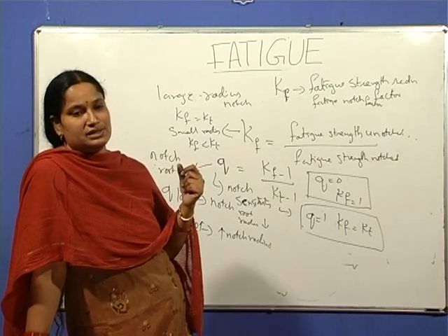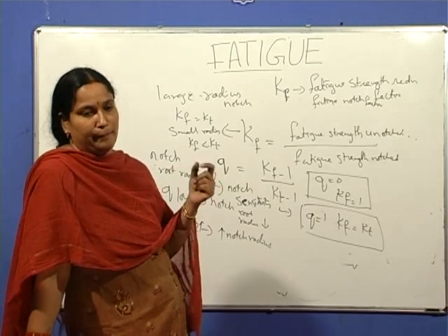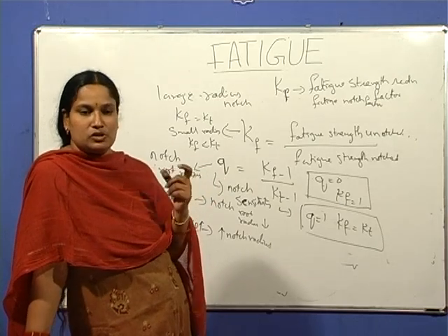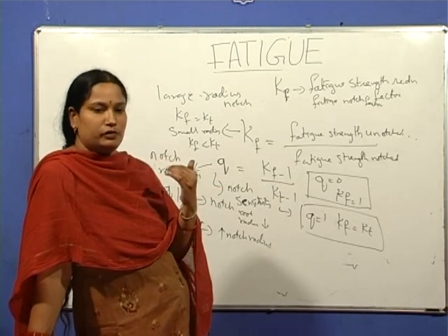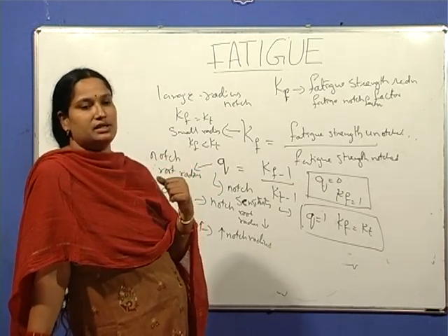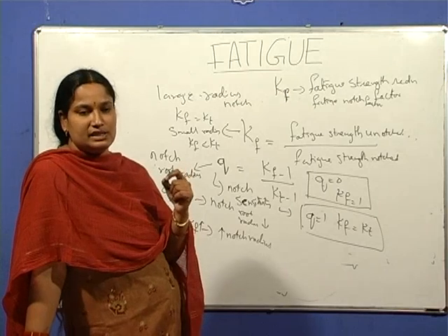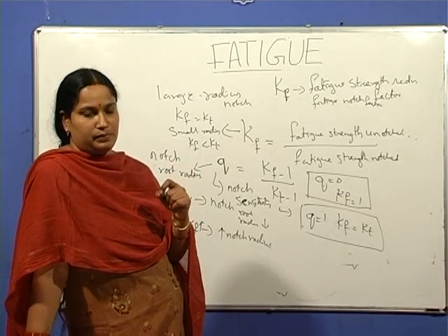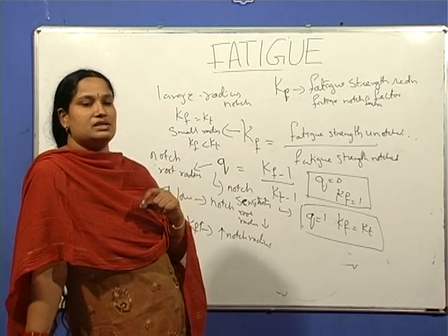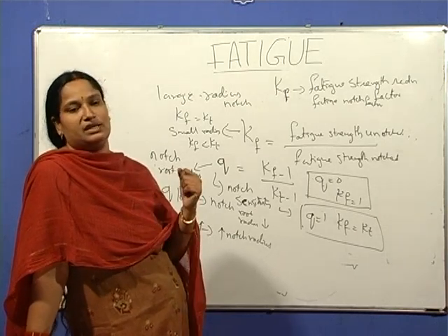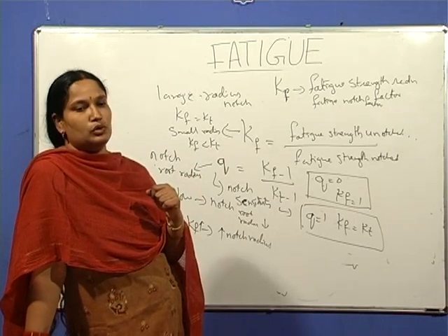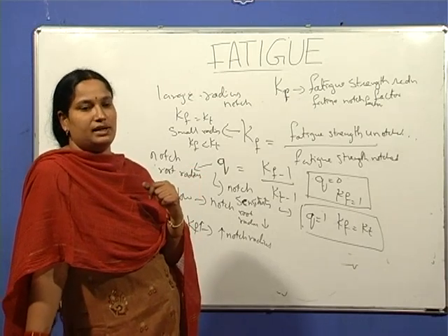High strength materials are more affected by these stress concentrations because of the limited capability of deformation for high strength materials and large increase in the plastic zone at the crack tip. High strength materials are more severely affected by the stress concentrators when compared to low strength materials or highly ductile materials.